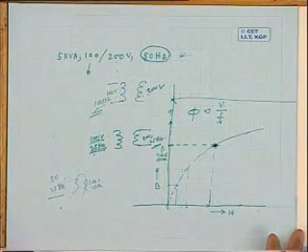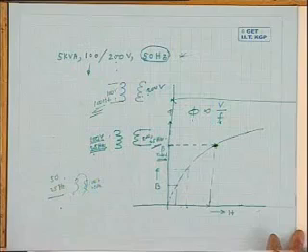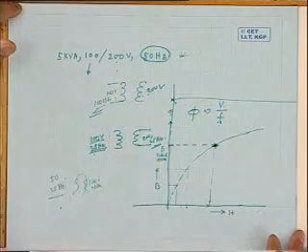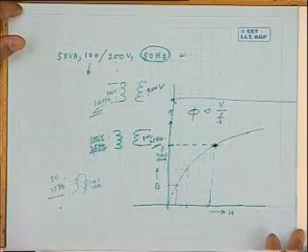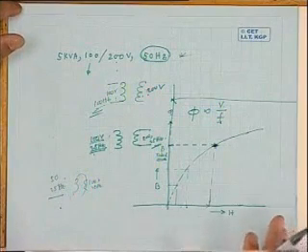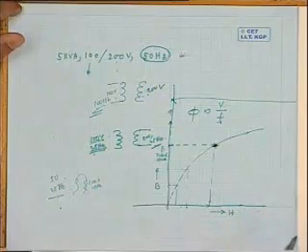We will see also this is true in the case of an induction motor, that if you want to control the speed of the machine, and frequency is controlled in the lower range, then you have to reduce also the supply voltage in the same ratio in order that the flux level remains constant. Magnetizing current drawn from the source remains constant. Are you getting?